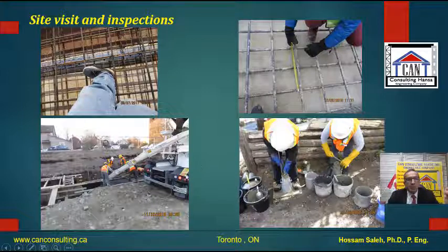What are the tests which we carry out on site? You can check the delivery time of the concrete truck. You make sure that the time is not longer than what's required. Most of the time, we specify 2 hours for concrete transport, or 2.5 hours sometimes, but most of the time 2 hours, to transport the concrete from the batch plant to the site.